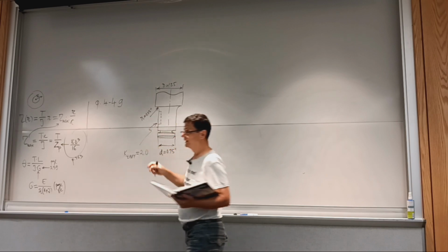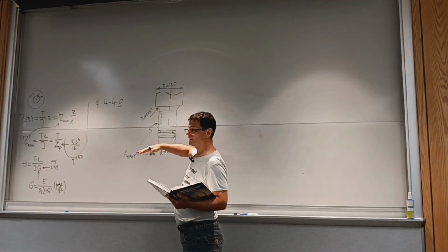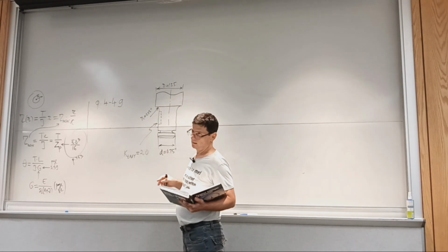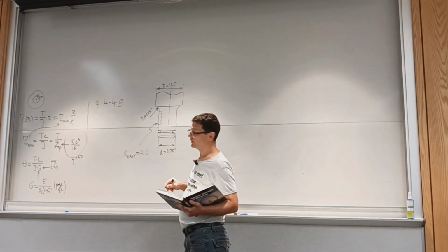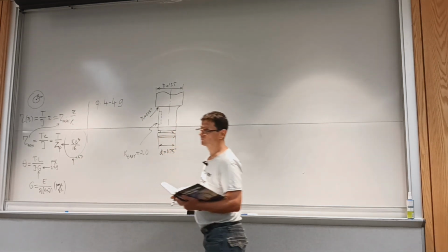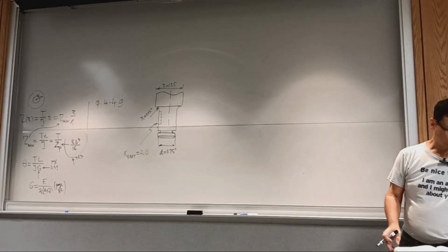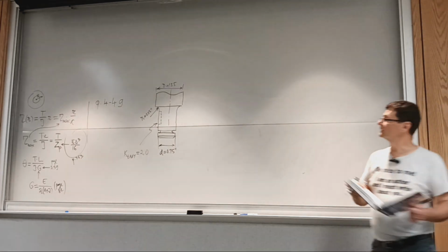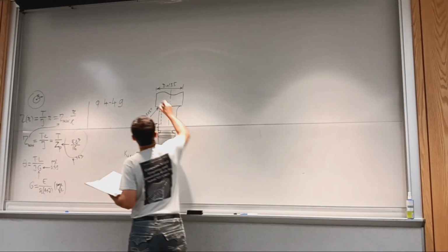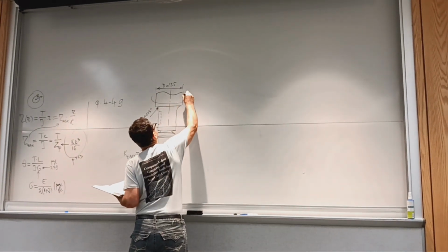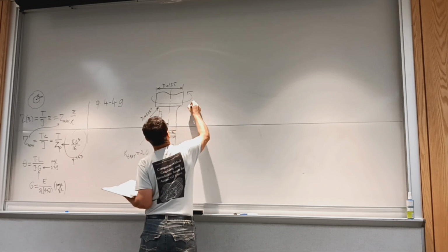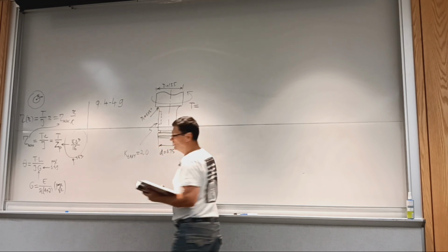The groove is below the blade and it's not loaded in torsion. So it's a good location for a retainer ring because there's no torque there. But we need to calculate the torque that's loading the shaft and resisted, of course, here at the blade.